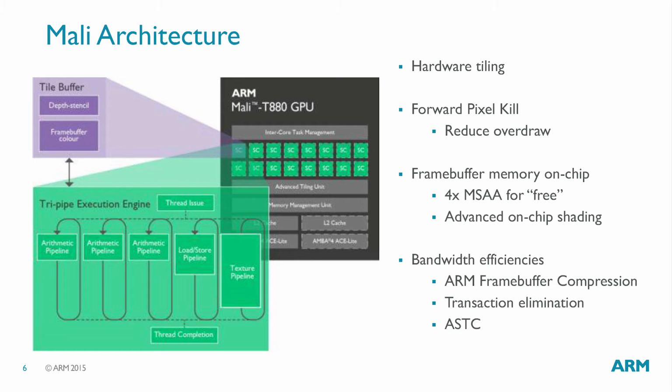So in practice, it kills pixels that you've already started rendering, wherever they are in the pipeline, once you realize that something is going to overwrite them. So this, in practice, gives you a lot of overdraw reduction. It removes the need to try and figure out what Z is up front. So modern Mali architectures, not the 400 series, because that really was focused on extraordinarily low power, but all of the GLES 3 capable devices have this sort of overdraw reduction built into them.